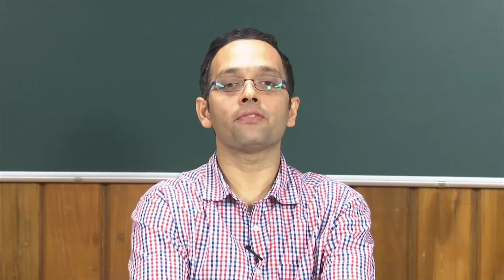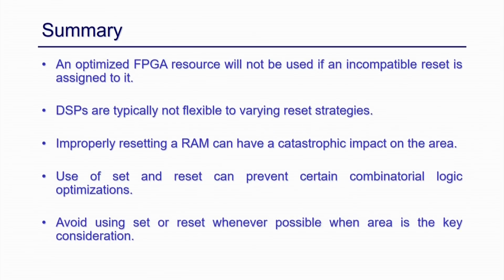And also we have discussed several strategies for how to use the reset and set pins of different components of FPGA devices, so that you can map better in the FPGA. Specifically, we have discussed the shift register: you should not use reset for a shift register.